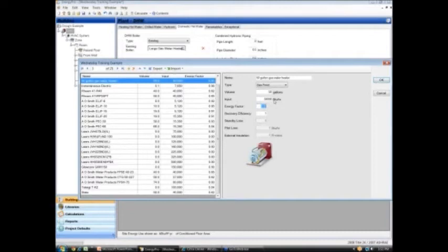I'm not going to get into how you figure out these energy factors right now. When you're looking at a 10-year-old water heater, it's a tough one to know that answer, in all honesty. I'm going to say it's 0.52, and I'm glad that we're muted and you can't ask me why I'm selecting that. I'm selecting a number here based on an energy factor. It's one of the inevitable problems we have with old existing equipment. We don't have energy factors for them listed or published anywhere for the most part.